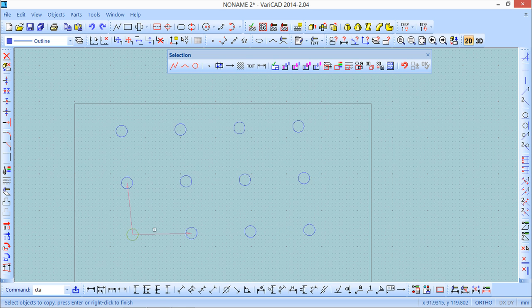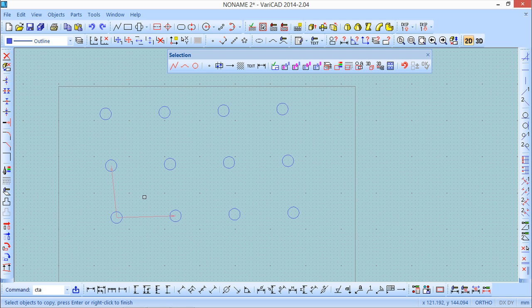So what it made me, you can see that following the directions I supply, and those 2 points, the first one, the origin, and the final point, it marked me the distance and it marked me the direction in both axes. And on the dialog box, I was able to give the information about number of rows, 4 in this case, and 3 on the columns.